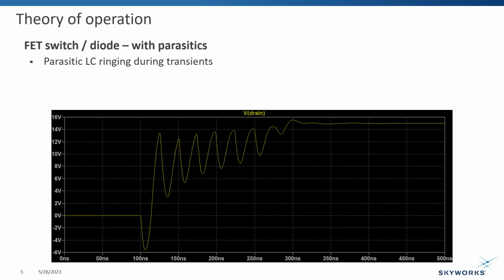The parasitic elements are causing a ringing, which is undesirable for several reasons. This ringing has energy which will leave the system in the form of dissipation. The amount of this energy is proportional to the switching frequency by nature. The amplitude of the ringing is related to the current flowing on the switch. This means that at high loads the power loss will be significant.